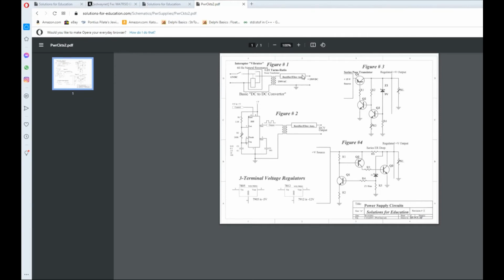Then you run it through the typical filter, and your vacuum tubes are nice and happy. And of course, you had to be careful because your tubes had 6-volt filaments, and people that took a 6-volt radio out of their old car and put it into a 12-volt car wondered how come it didn't work anymore. And these, you could actually hear them.